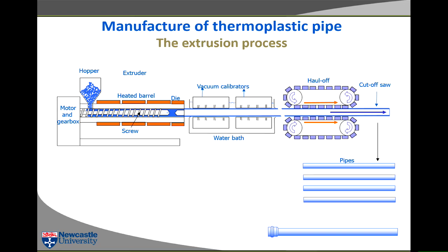So if you want to make a thermoplastic into a final product, the melting and shaping process is actually quite complicated. You have to do some special things. Stuff comes as granules of thermoplastic. You could try putting them in a beaker on a hot plate or a Bunsen burner. You might think this would melt the polymer. In fact, it wouldn't. It would simply decompose some of the polymer, because one of the problems with thermoplastics is they have such low thermal conductivity that they're sometimes used for insulation.